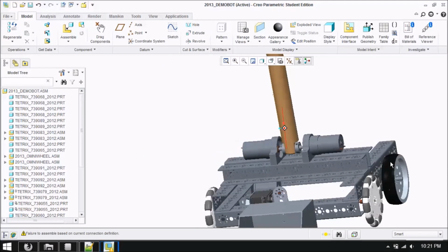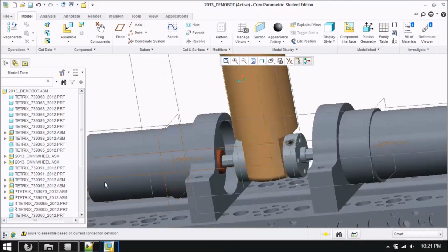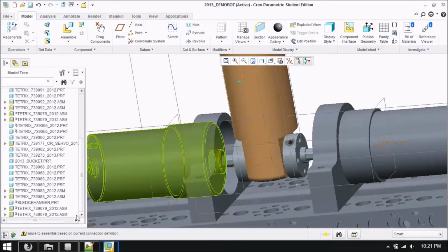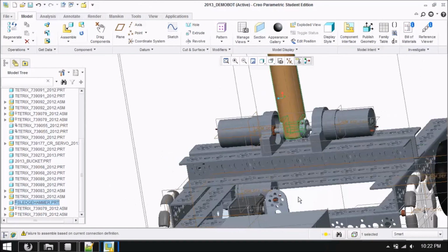These last two brackets that I added here and here, if you look at the side menu here, you can see that they've got this weird little square beside them, and also so does the sledgehammer. And what this square means is that it's not fully constrained. You saw when I accepted for these three objects, they were still purple instead of orange, and that means they weren't fully constrained. And what that means is they can still move around. I didn't add enough constraints to make them in a solid, non-movable spot.